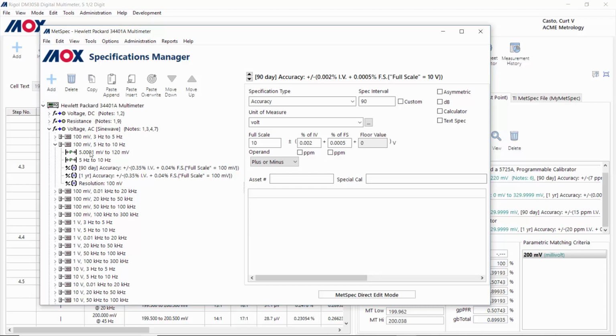The fact that this is millivolts and the qualifier is frequency makes it an AC range. If it were the other way around, with frequency as the first parameter and millivolts as the second, we would be talking about a frequency range because the quantitative parameter would be frequency. The reason I'm going into such detail on this is that it's very important to understand how MPS is actually going to use this information to find suitable ranges for calibration standards for you automatically.